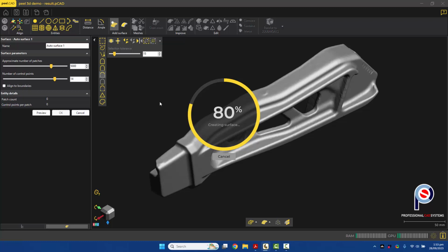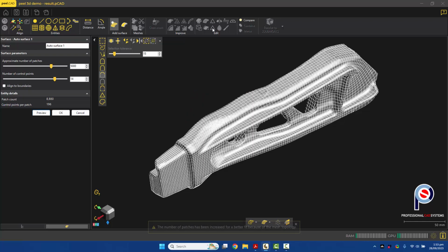So while we're waiting, these are all the primitive entities you can add. We can copy meshes, we can duplicate them. Under improve, we can edit boundaries, reduce triangle count by decimating, hole fill. We can surface offset, we can offset boundaries, cut meshes with a curve, mirror meshes, flatten a 3D surface, sculpt, rewrap a mesh watertight, scale an object. So edit's quite powerful.